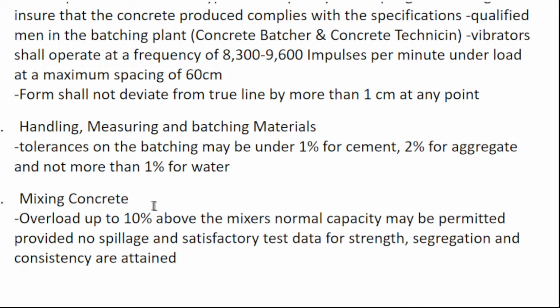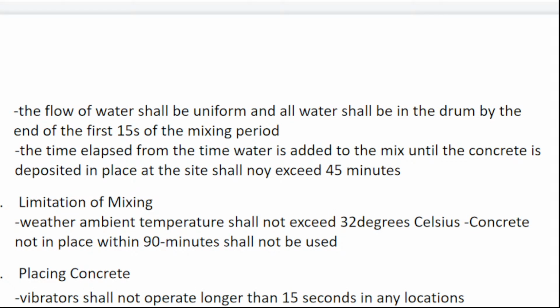Okay. Mixing concrete, overload up to 10% above the mixer's normal capacity may be permitted, provided no spillage and satisfactory test data for strength, segregation, and consistency are attained. 10%. Okay. Flow of water shall be uniform and all water shall be in the drum by the end of the first 15 seconds of the mixing period. Even the process itself, there is a procedure. Within the first 15 seconds, the water must be there